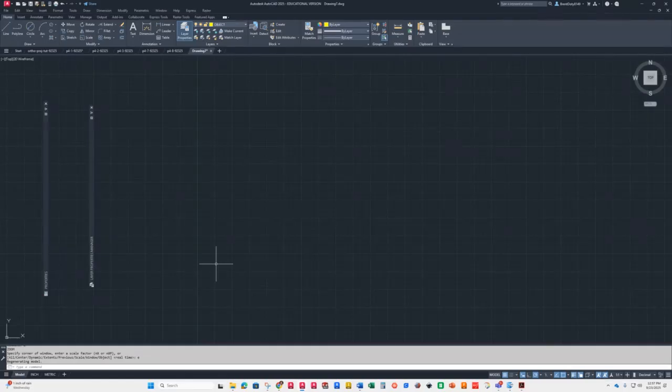Used to, the limits didn't mean as much, but for some reason now, once you get so far out of the limits that are set, it won't draw. Literally will quit drawing. You'll try to draw a circle and it won't let you, or you'll draw a line and it won't let you click the end point. So you have to adjust them. That's why.